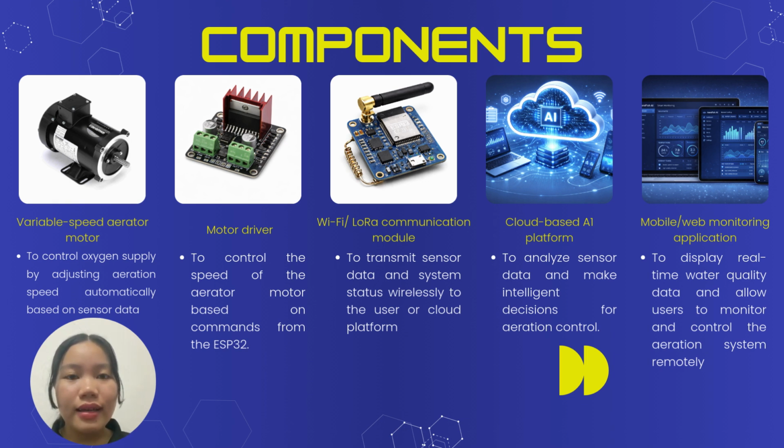Next component is the variable speed aeration motor. It controls the oxygen supply by adjusting the aeration speed based on sensor data. Next component is the motor driver. It regulates the speed of the aerator motor according to the commands from ESP32. Next, the Wi-Fi and LoRa communication module transmits sensor data and system status wirelessly to the user or cloud platform.